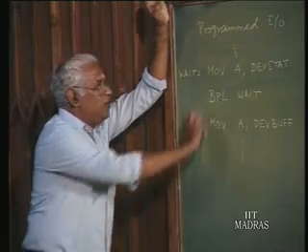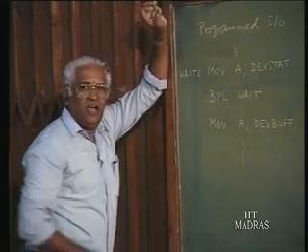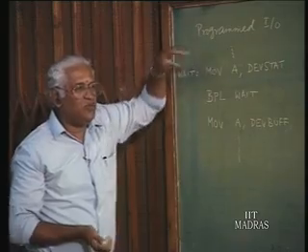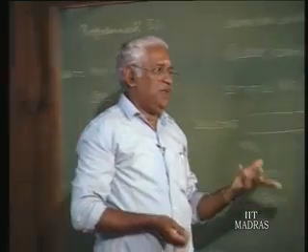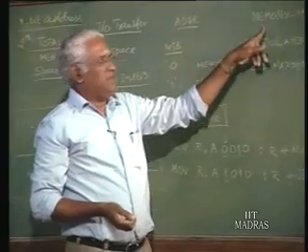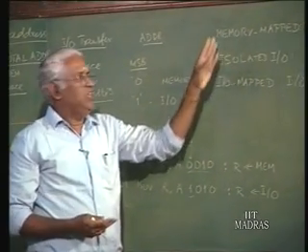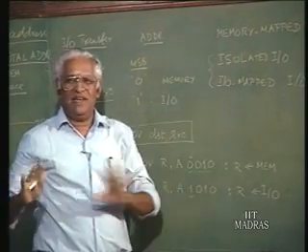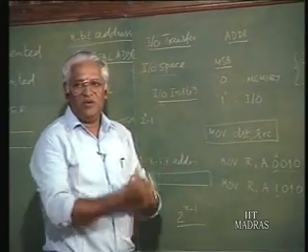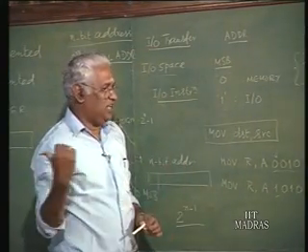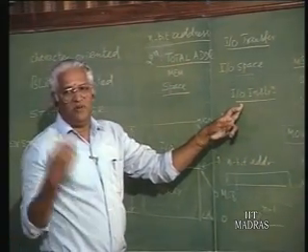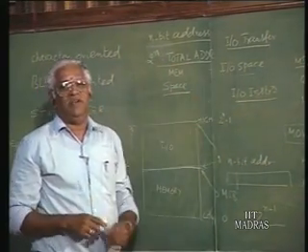Now, you just see with one instruction I am doing IO, and the same instruction I can also use for memory referencing. That is essentially because I am following a memory mapped IO. If you have isolated IO, slightly the program will alter. You will have to use the in and out instructions depending on what the device is, if you are having a separate IO space.